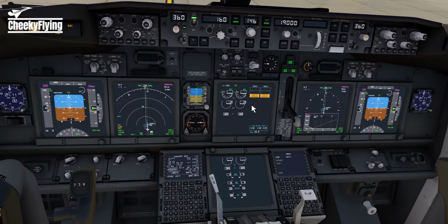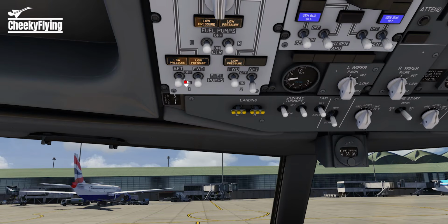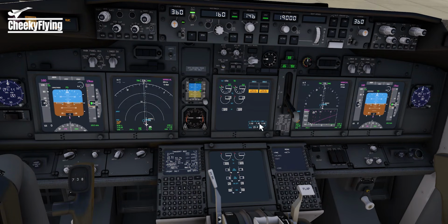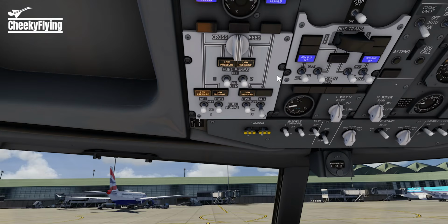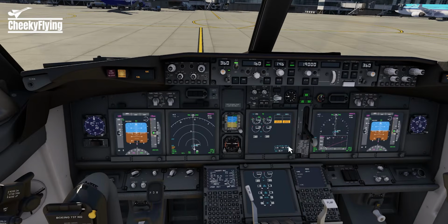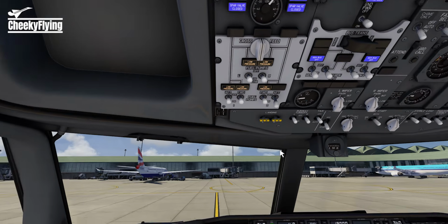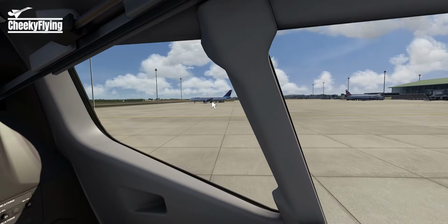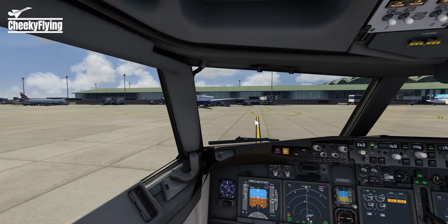I've heard from my friend, he once told me that in order to know which ones to flick, you need to check here and see which side of the tank has more fuel. You'll turn on the fuel pumps for that tank, so the APU will just burn through the available fuel on that tank. Let's say it's on the right side, so you turn one of these on, if I'm not mistaken. So that's it, and we are now ready for the engine start, since we are already facing out towards the taxiway.